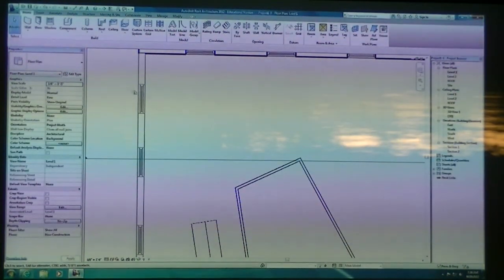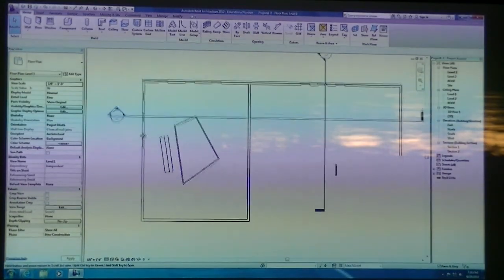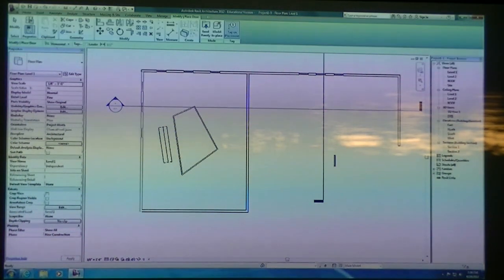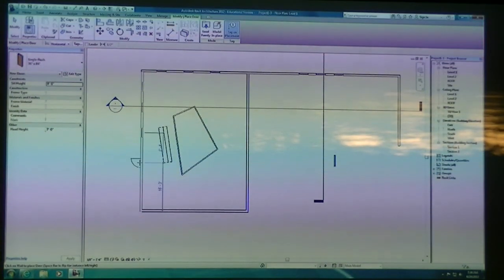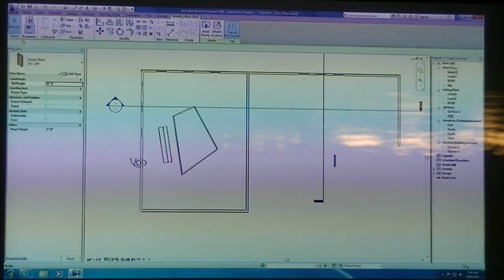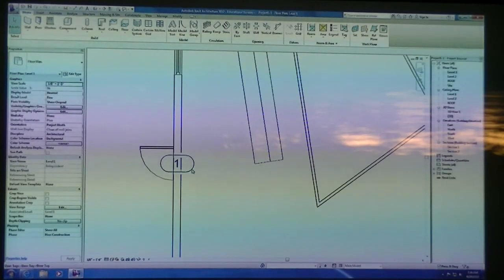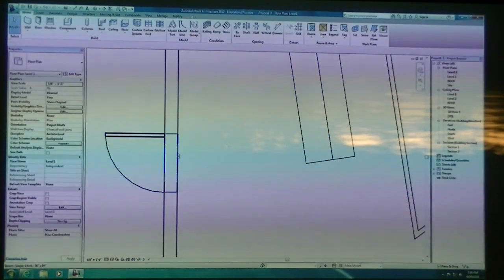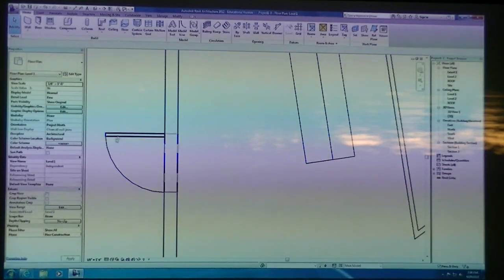And then if I were to take, let's say, this one particular wall, I'm going to add a new door, and I'll just use whatever just came with Revit and stick it in here. By default, Revit already dashes in what's going to be demolished in order to put in this door.